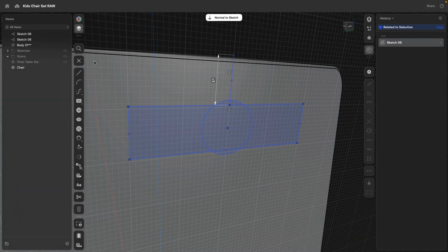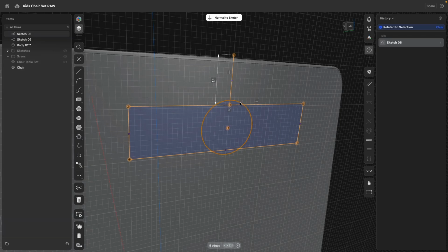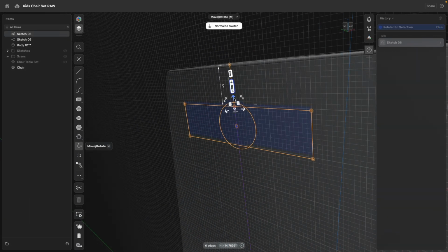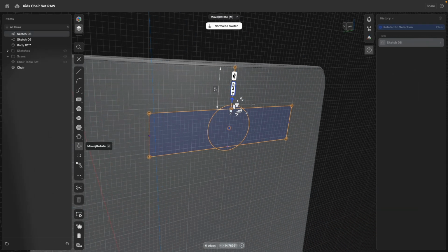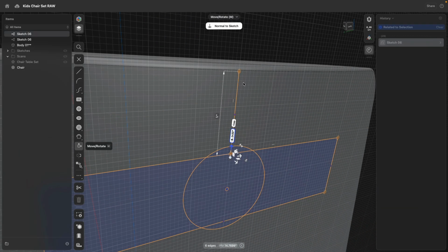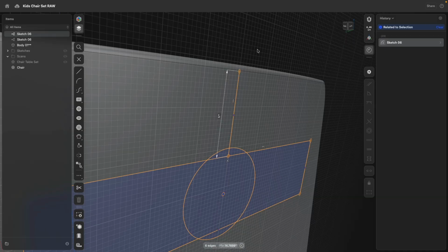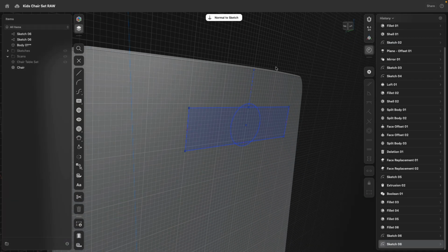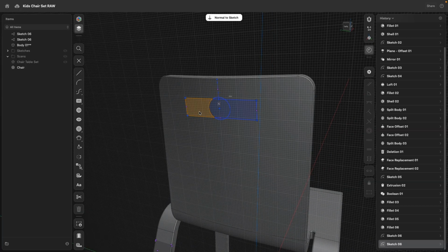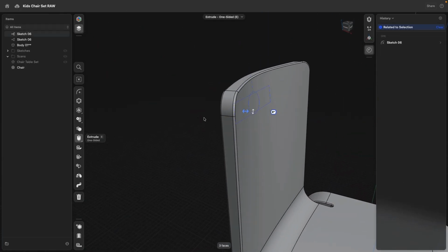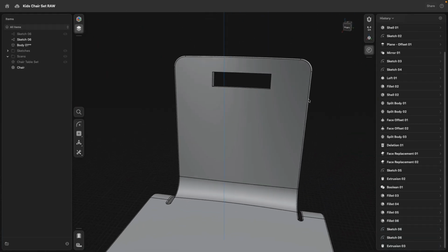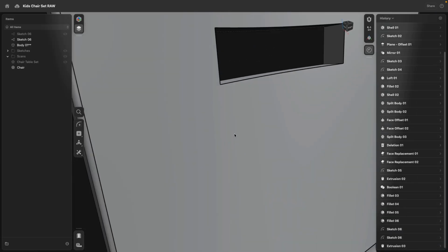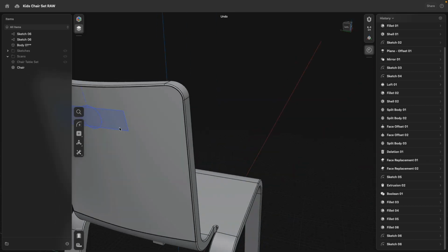Very good. Now I can select everything inside the sketch. I can use the move command and, for example, move this down. And I use this line as a reference to plot somewhat where the position would be. We can make this a construction, so it doesn't do anything. Yeah, and then we can test. So these two openings, cut through. Okay, now this is maybe option A or undo.